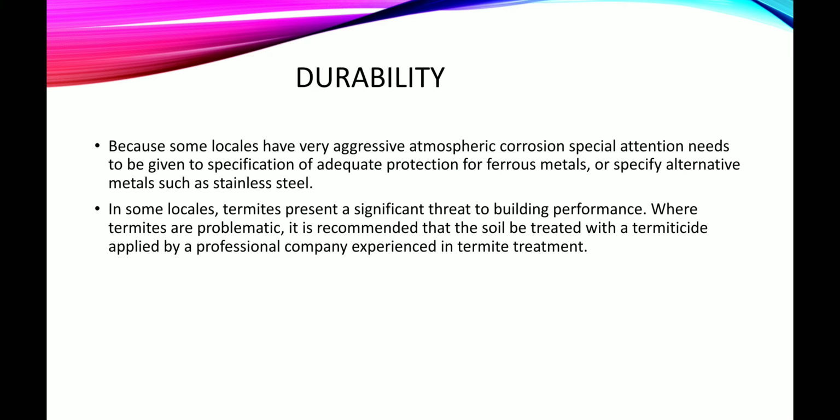Durability. Because some locales have a very aggressive atmospheric corrosion, special attention needs to be given to specification of adequate protection for ferrous metals, or specify alternative metals such as stainless steel.